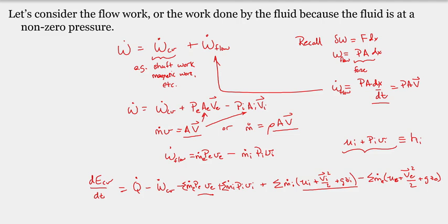And this is why. We defined enthalpy essentially as a shortcut in our accounting for the thermodynamic properties in control volumes. So if we look at these expressions here, what you see is that every single control volume, when there's flow moving into or out of it, which is the definition of a control volume, when you have mass transfer across the control surface, we have flow work.